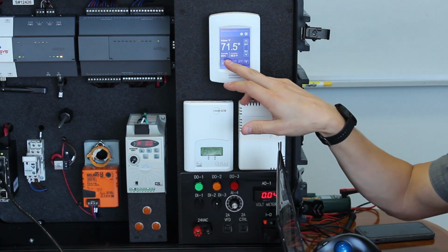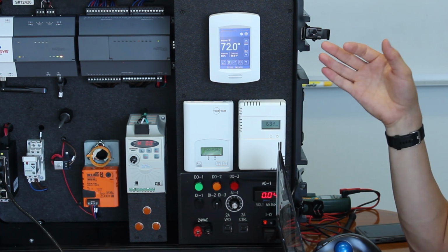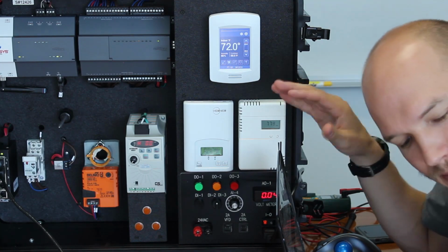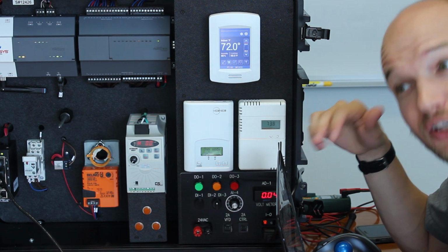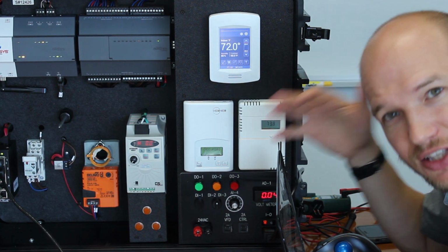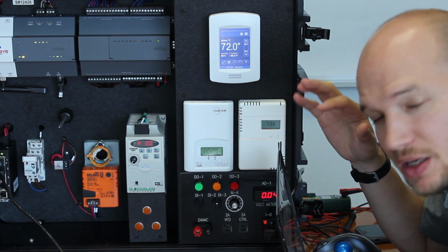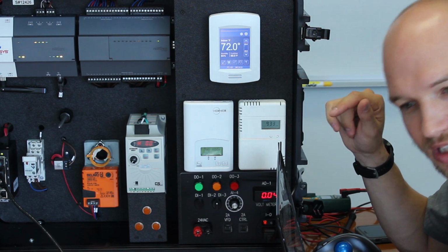So yeah, it's already starting to rise. It was at 47, it's at 63, 65. And so as that rises, what kind of equipment will be required to bring that back down? It's too humid, so we need to dehumidify it. So a dehumidifier would be needed in the system to bring that back down to that 40 to 60%.